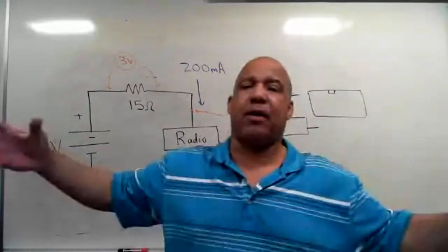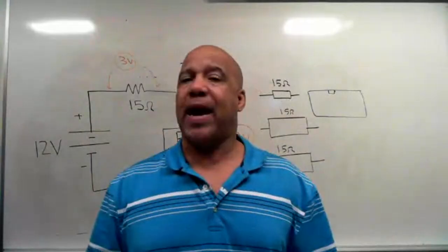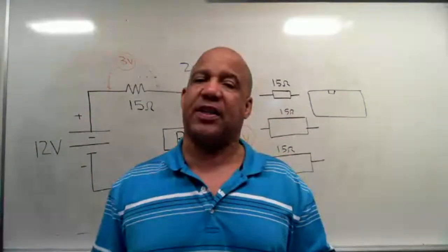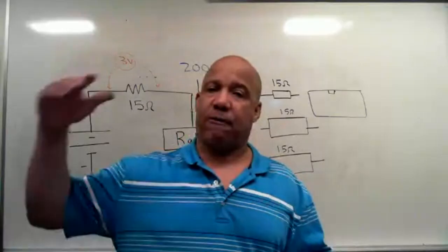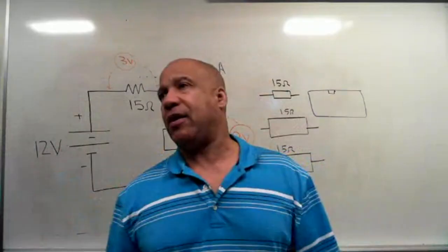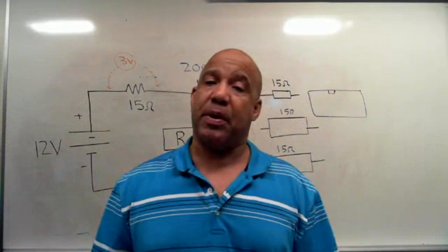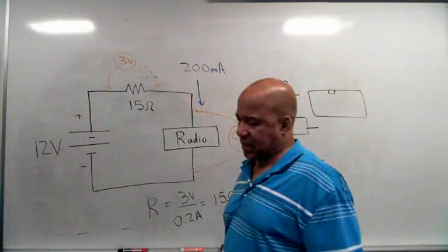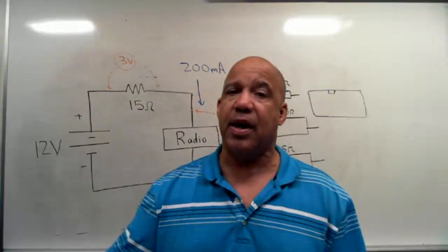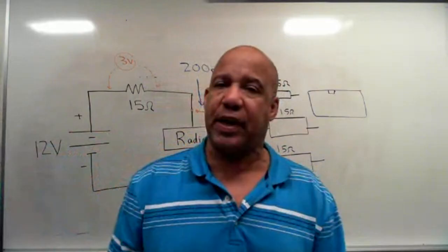So if I can't make something bigger to increase the surface area, I can leave it small, but I got to have some kind of fan to take the heat away. Air is a fluid, and the fluid moves away, as it does through something called, in physics, convection. Heat is transferred from the thing we're talking about, in this case the resistor, to the air and moved away from it. And the final way to do it is moving an actual antifreeze-type substance, another fluid, because you can actually pump liquids. Sometimes people with really expensive audio amplifiers have a special kind of antifreeze they pump into the amplifier to get rid of the heat. So some kind of way you got to get rid of the heat.